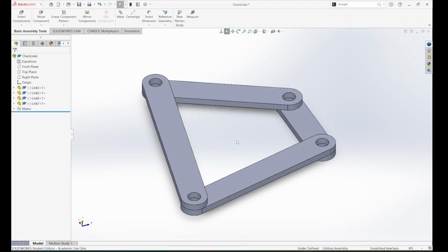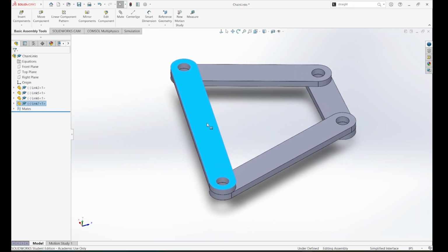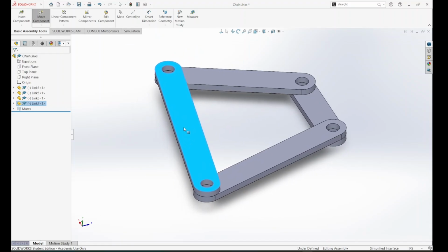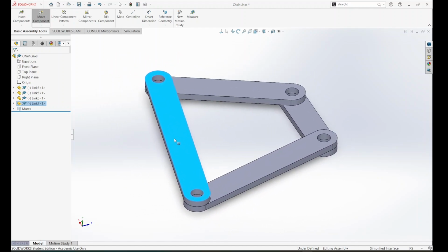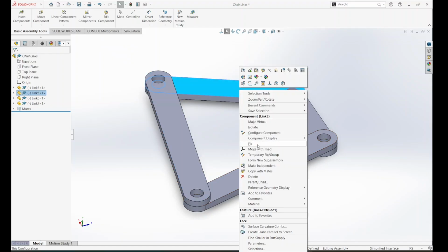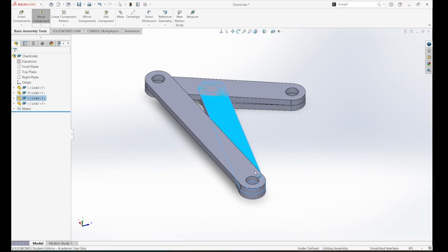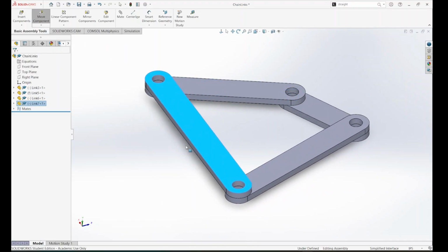So let's say we want to float everything. Now things get really weird because I'm not only moving it in the traditional XZ plane here in the bottom left, you can see I'm also moving it in the Y plane. So I'm moving it up, down, around, so there are no constraints on our object here. So it is always wise to at least fix one component of your assembly, so that if you have mates or interfaces, they behave correctly.